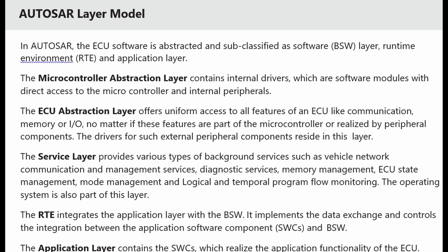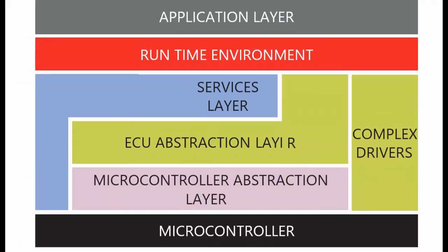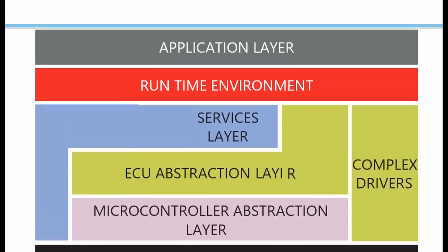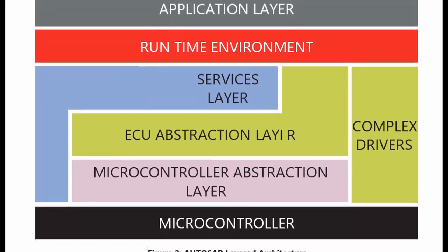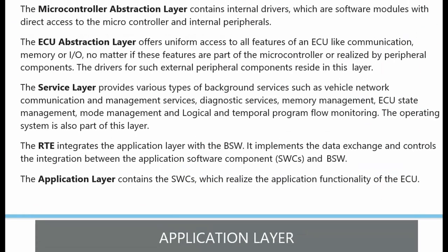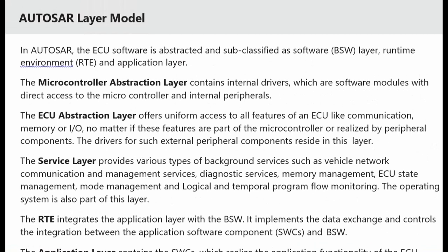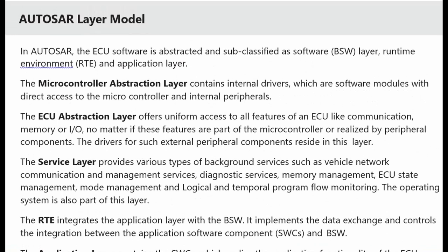Here you can see this AUTOSAR layer model. So here we have the application layer, runtime environment, service layer, ECU abstraction layer, microcontroller abstraction layer, microcontroller, then complex drivers. From this, I'm going to explain each of these.